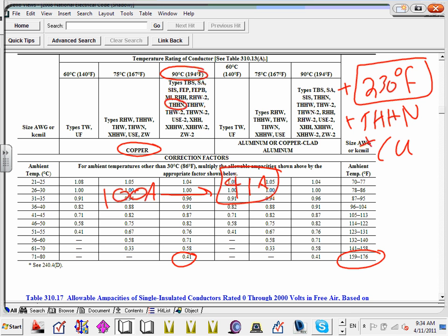So, long story short, guys, don't group feeders, 100 amp or more, that's in my definition, commercial feeders. Don't group them, because that'll screw you up. And branch circuits THHN, don't put more than 16 hots, plus the neutral included as a hot, in a 3/4 of an inch, which is plenty. If you stay within this parameter, 16 conductors, number 12 THHN in a 3/4 of an inch, and the feeder is dedicated, then you don't have to worry about this mess at all.